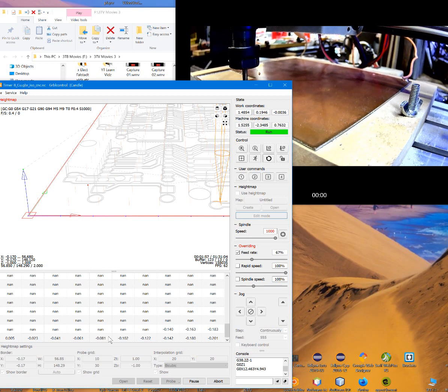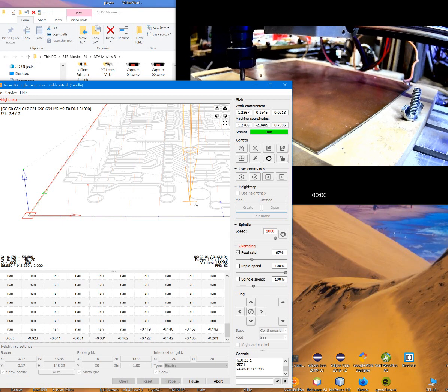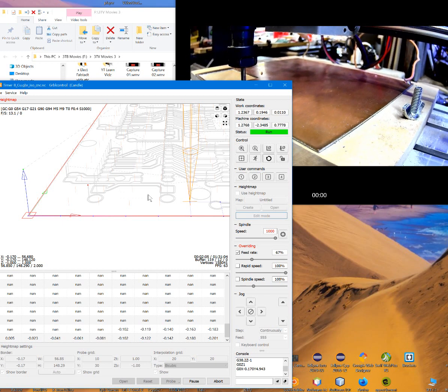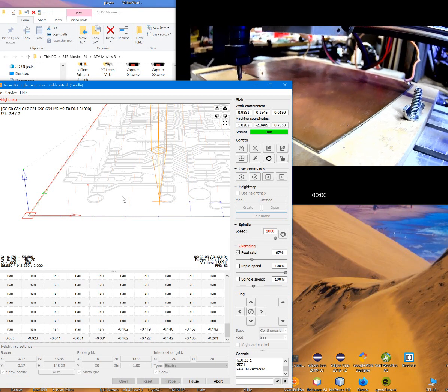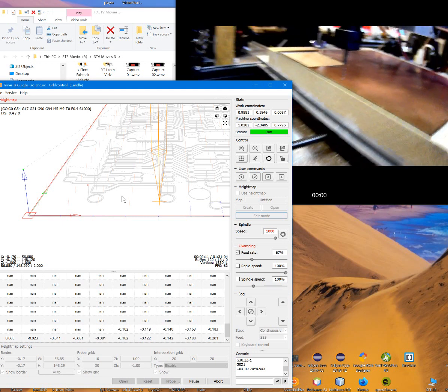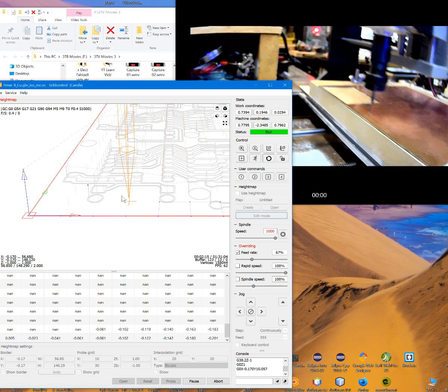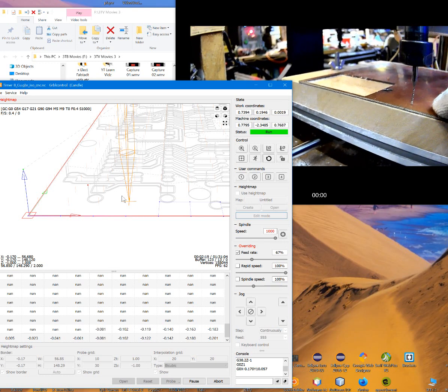But by keeping that in mind, for example, if this actually had a hole and it accidentally probed into that hole, and you were quick enough to stop it. A lot of times if I see a hole, I'll take a piece of nickel strip or something, just to stick it below the bit when it's probing over that hole.